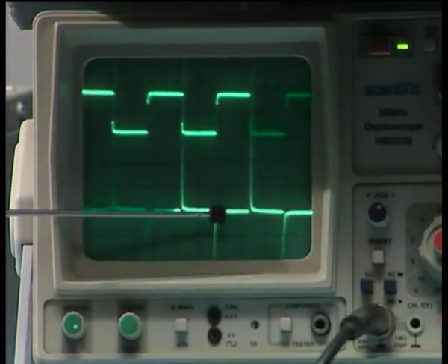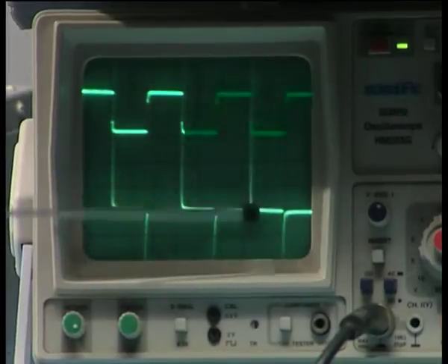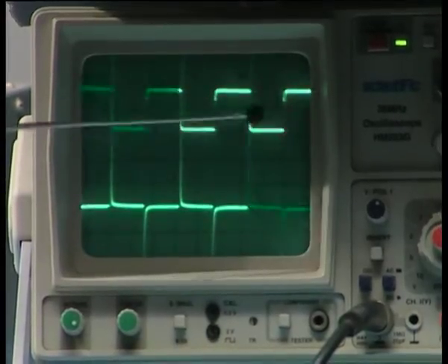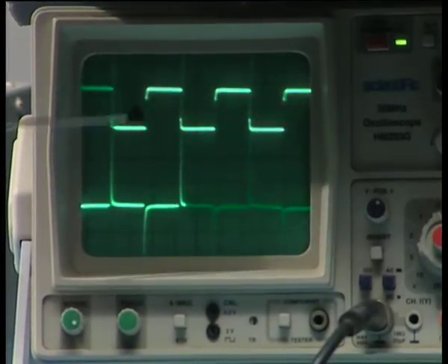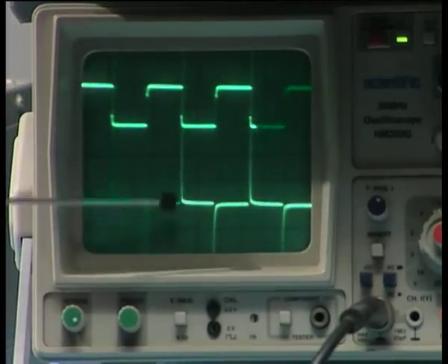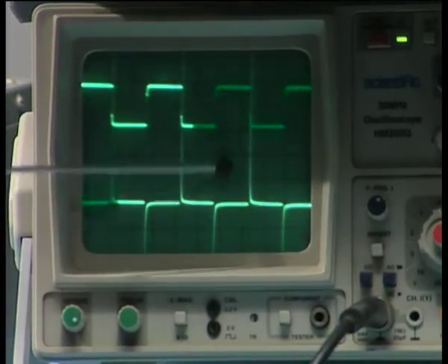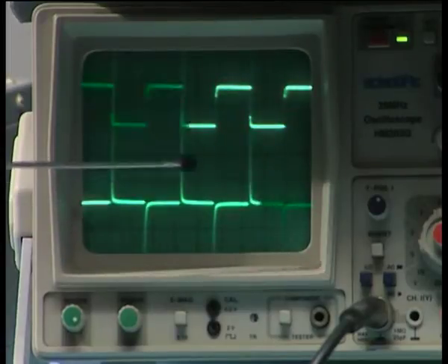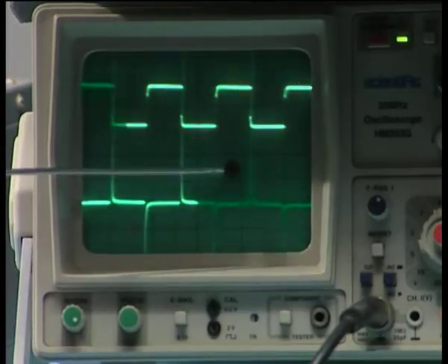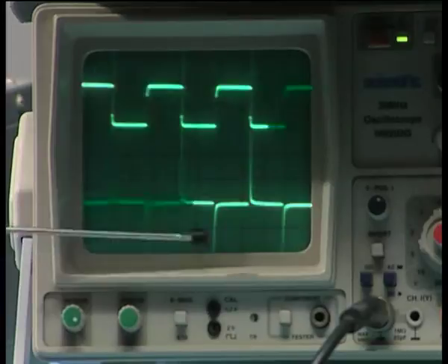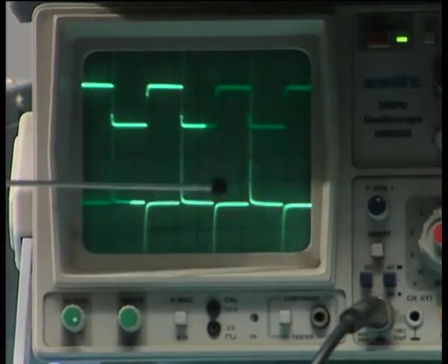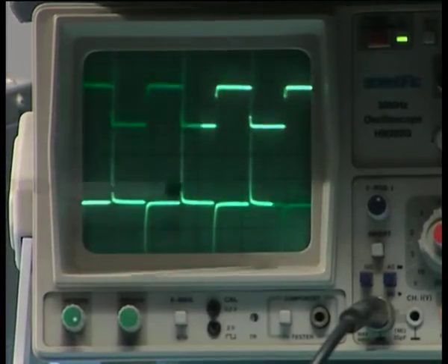So, this is the output waveform with sharp spikes at these transitions, and the square wave therefore gives me very sharp pulses. If I put a diode, I can get rid of either the bottom pulses or the top pulses, and I can use it for triggering other circuits.